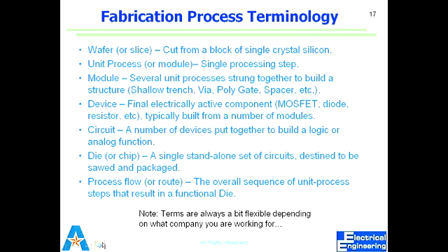Dr., I have a question. When you use ICs, you usually end up putting capacitors and resistors, etc., around them. Is that because you want some form of external control, or because some resistors and capacitors are just too difficult to build into devices? They're probably not too difficult, but for flexibility, we don't put them on the IC itself. So that same IC can be used for flexible ranges of resistances. You don't want to hard code it, so to speak. It's the same thing we do in software; many things we don't want to hard code, we want to leave for user input. Same is the case for that. Makes sense? Makes sense.